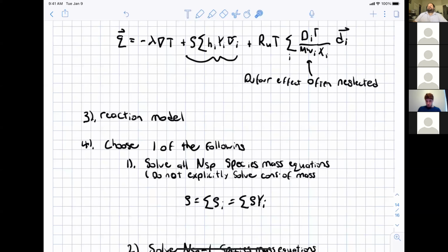You cannot use a methane air reaction model that was calibrated for stoichiometric combustion at 1 atmosphere to model detonations. You cannot use them to model fuel-rich detonations where the equivalence ratio can be, say, 2, and the pressure can be on the order of 100 atmospheres.